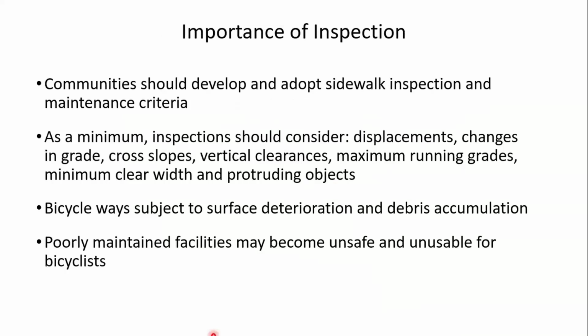So I mentioned inspection. I think municipalities should develop and adopt sidewalk inspection and maintenance criteria that consider things like the displacement, the changes in level we talked about, changes in grade, cross slope, vertical clearance, the protruding object issue, maximum grades, minimum width, and those sorts of things. So that, to me, is what should be included in inspections.